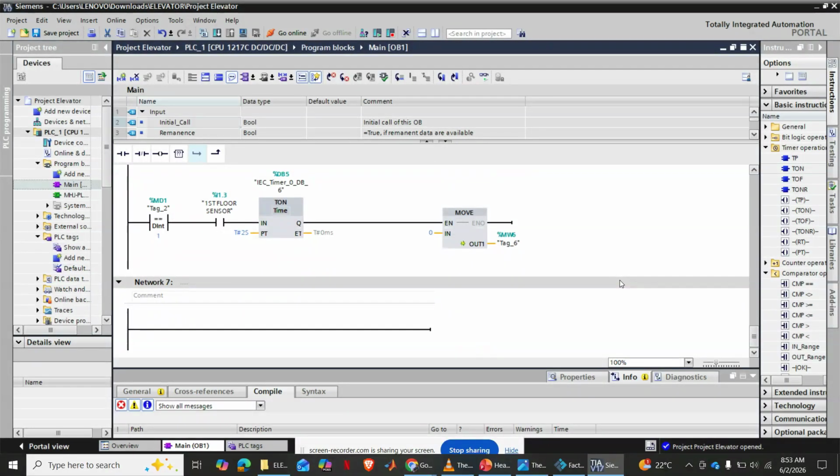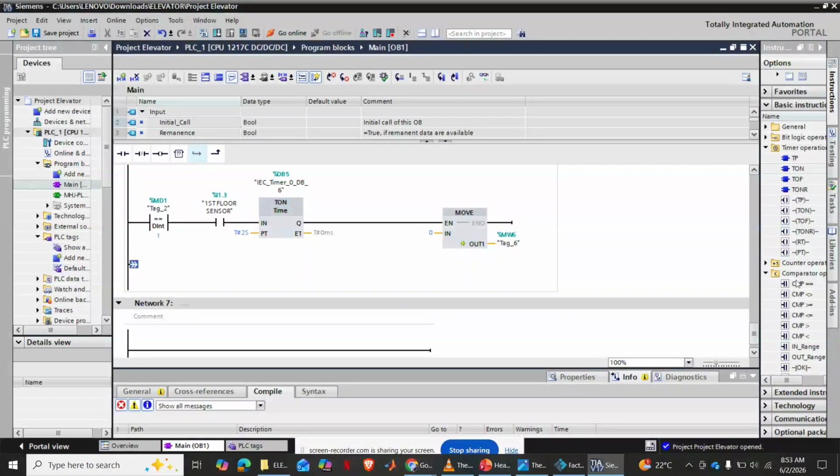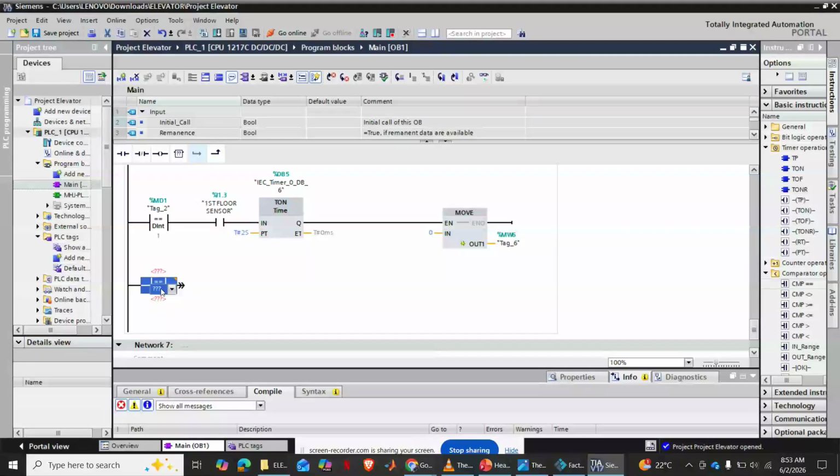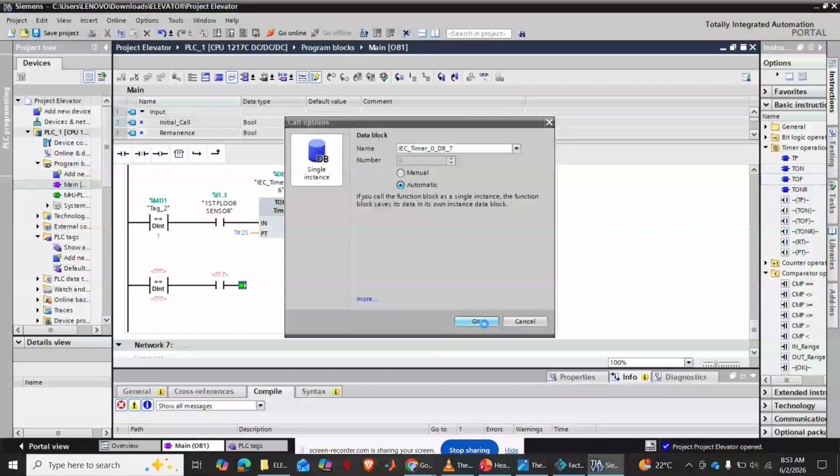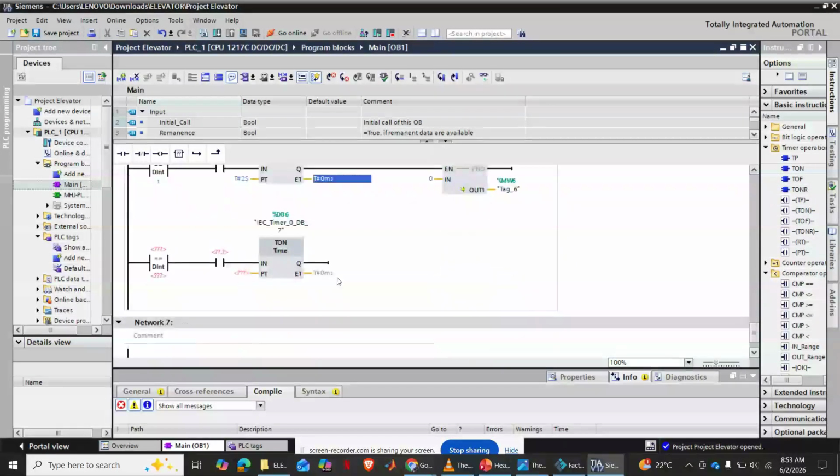All right. Again, we go to the second flow and third flow the same way. On the second flow, here we will have a comparator like this, and then here double integer. Then here we'll have our second flow sensor. We'll have a timer on delay, and we'll have an output as a move. We move 0.